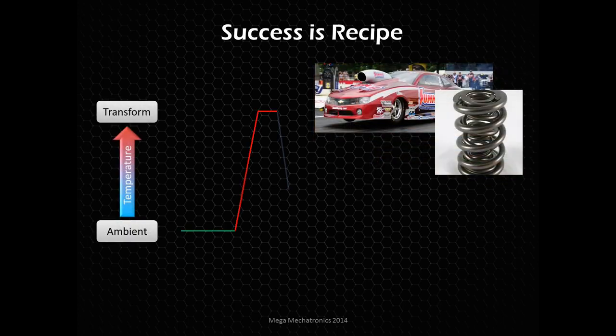So again, looking at this chart, an example process for a high-performance valve spring would look something like this, where there's a hardening, there's an austemper where we're not bringing that all the way down to room temperature and we're not quenching it, and the quench rate is a little bit slower because we're dipping that in some molten salt and holding it at a higher temperature.